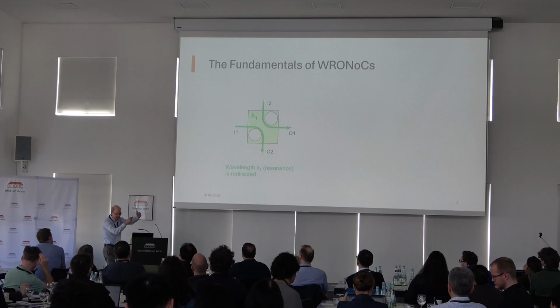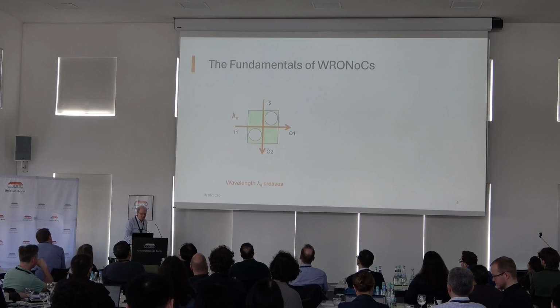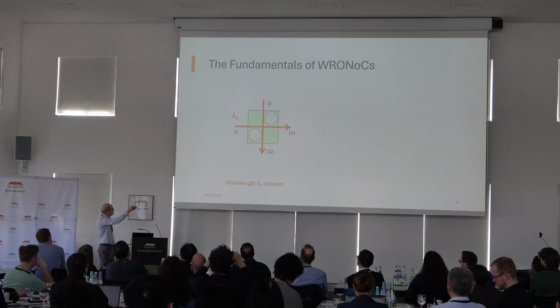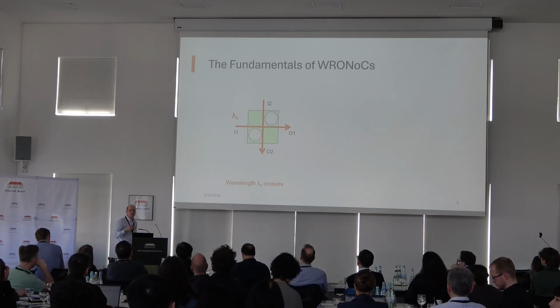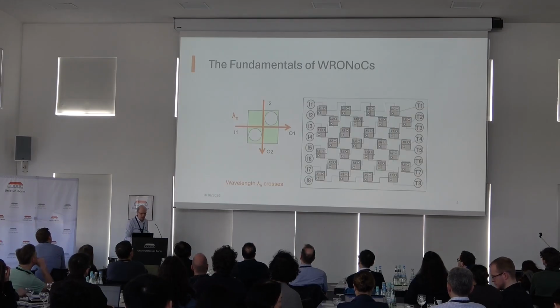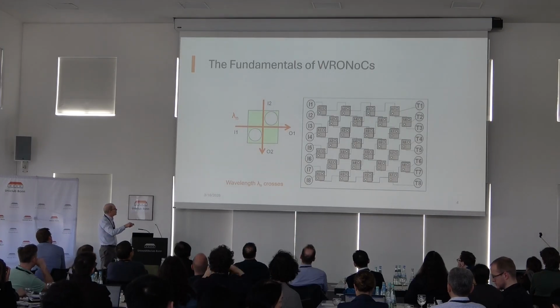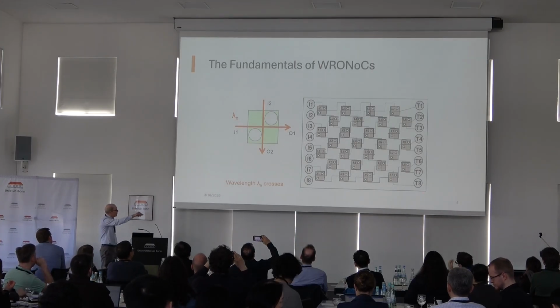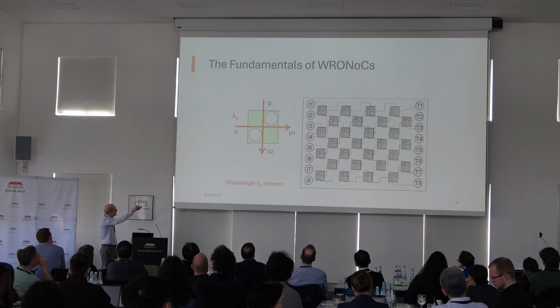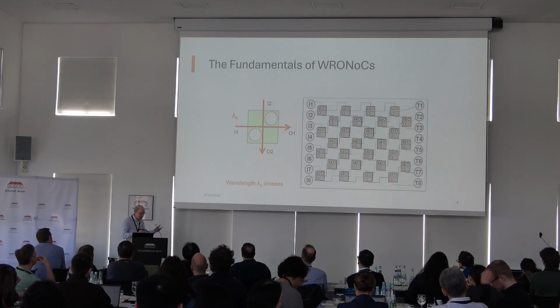In this case, you can also have 180 degrees or 270 degrees deflection. So if I then have another wavelength, lambda n, which is not on resonance with these microring resonators, those go straight through the signal. And this is how we affect the routing in a photonic system. So for example, this is a so-called 8 by 8 because we have 8 initiators and 8 targets, lambda router. And you see all these photonic switching elements, about 25 or so of them here in the center. And this is resonant to lambda 1, this is resonant to lambda 2. So each one is resonant to a certain wavelength.